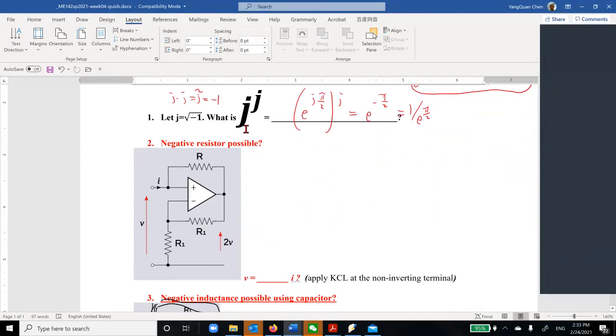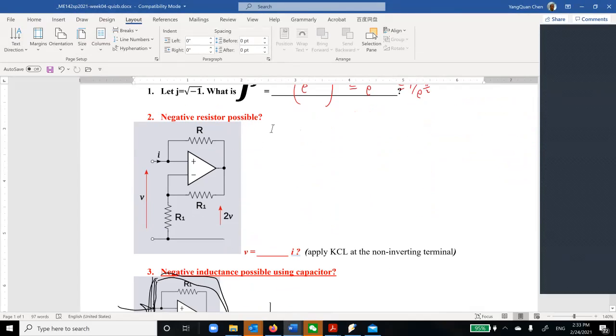Okay. So let's look at this negative resistor. So basically, I hope you will discover that V is some sort of a minus R equivalent, okay, here. So how we can get this one out, okay? Okay, so because this is V as my input, I care about I. So I can put this whole thing as a component, okay? This is my component.